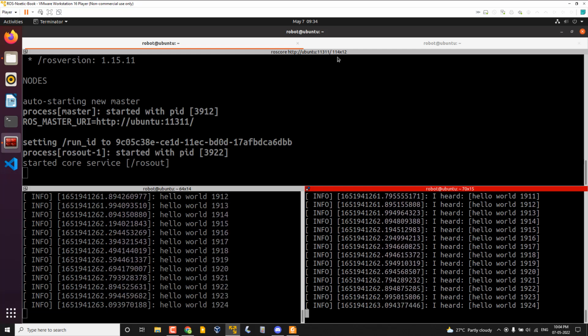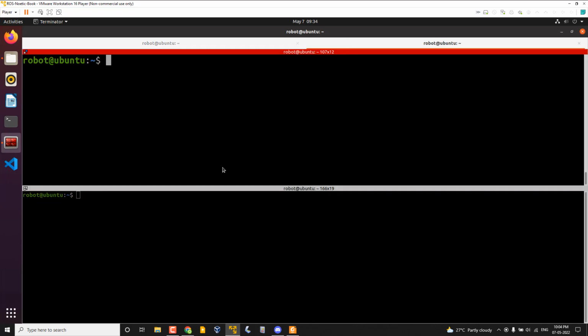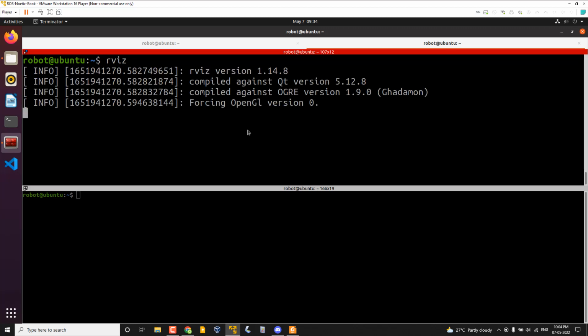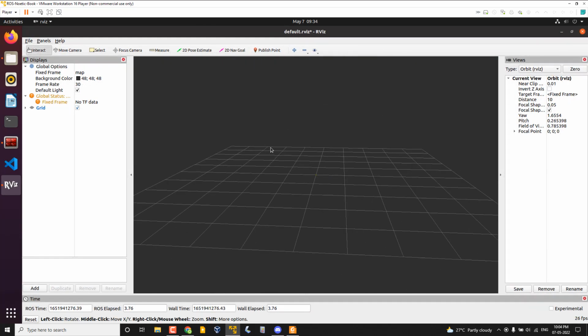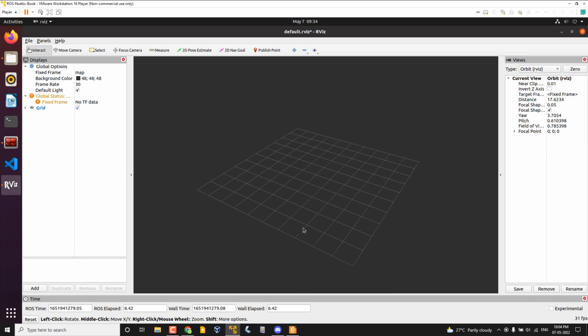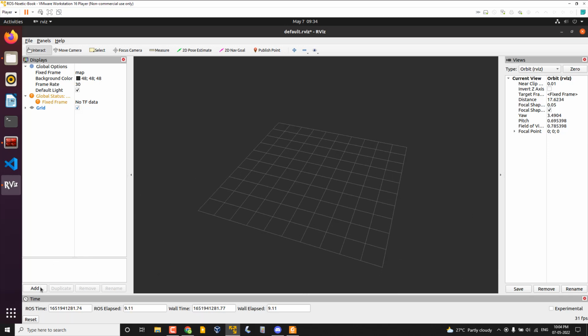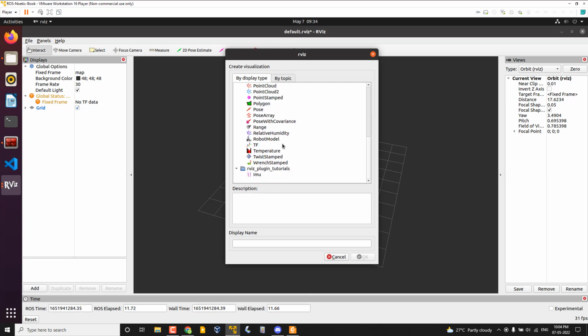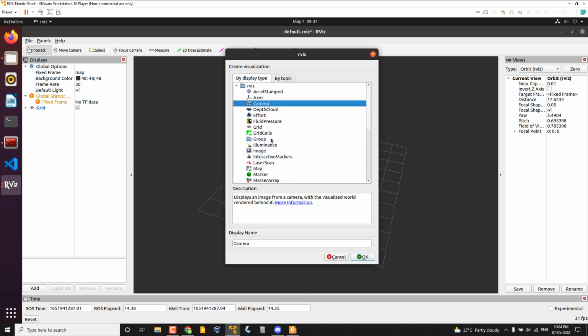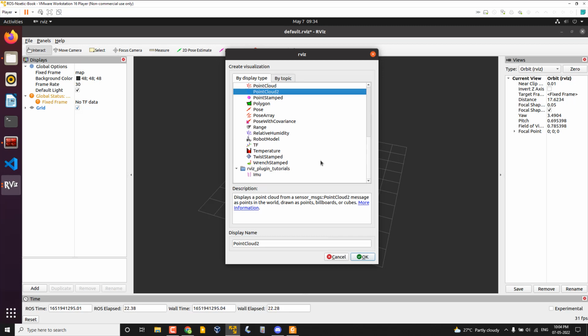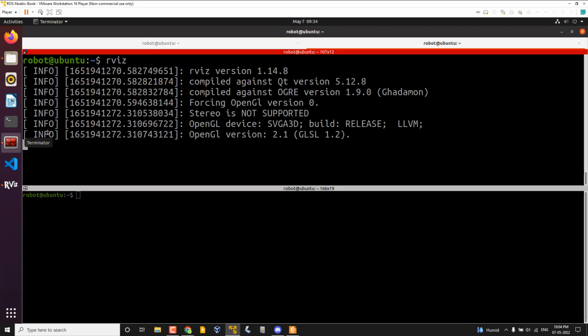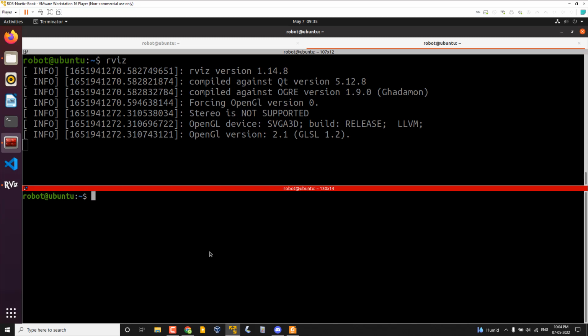And then the next tool, the last topic, is RViz. RViz has no role here, but I just want to show you. Simply type rviz on the command line, and you will find a 3D viewport. This is mainly for visualizing sensor data, like camera, map, laser scan, point cloud. All this information can be displayed, not like simple topics. Maybe I can show you a demo of RViz.